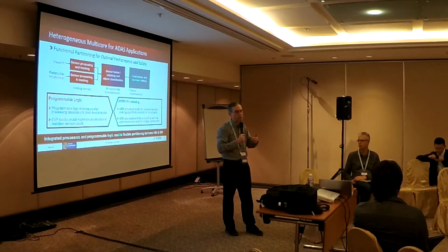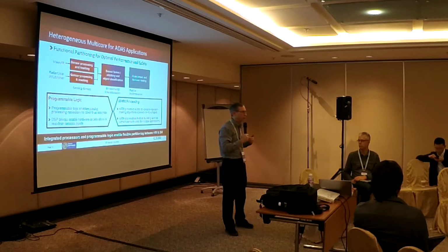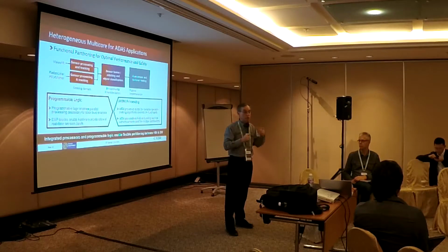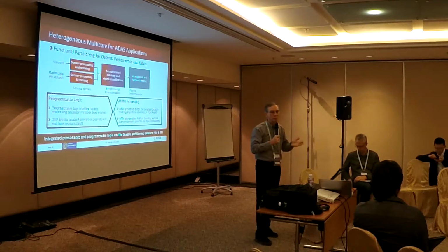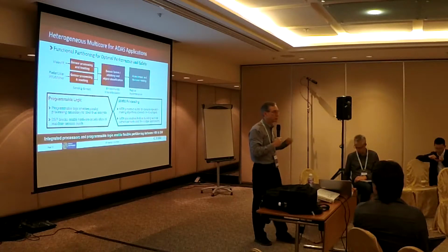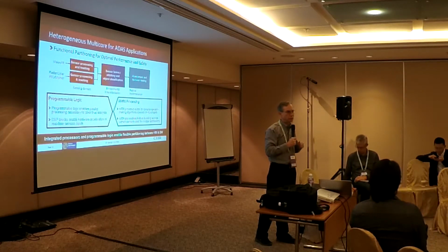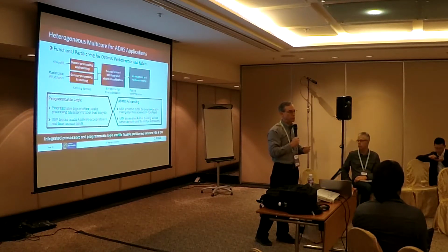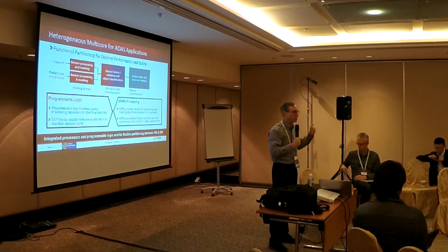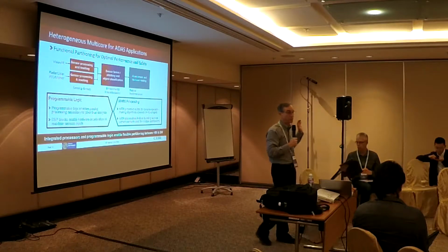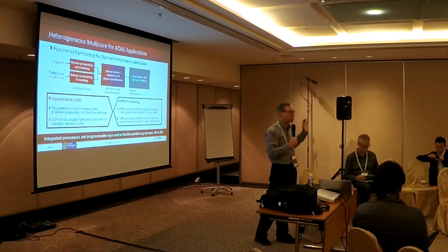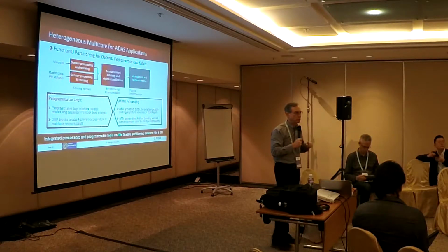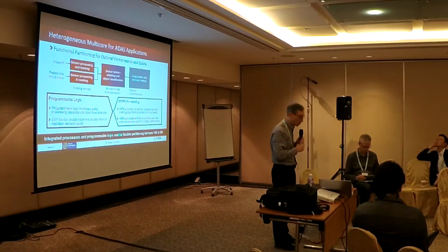You've got to make a complex decision with limited information, and that's probably a place where a good general application processor could be used. So something like the R5s can be making the final decision on the information that's coming in. Send that final decision information maybe to the platform management unit. The platform management unit goes and does a quick system-wide check, makes sure everything is healthy. Okay, there's been no single event upsets, nothing else that's strange going on, and then finally make that braking decision. It says go ahead and brake the car.